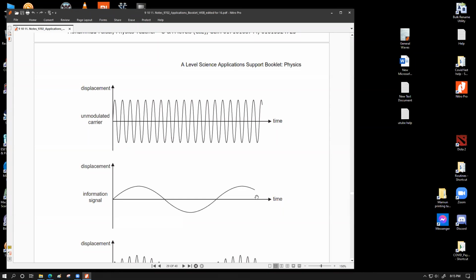For whatever reason, for maybe one second there is a silence, none of you are talking. Your cell phones, towers, everyone is prepared to do the modulation, demodulation, everything to transfer the whole signal, whole information. But if you are not talking through the microphone, do you have any modulation? You don't, because for that one duration of silence or quiet, you have no information signal available. So you basically have the unmodulated carrier, which is basically transferring through the channel, and you still have communication available, and you are still paying the network because they are willing to do the job, but you are not giving them any job. That's your problem.